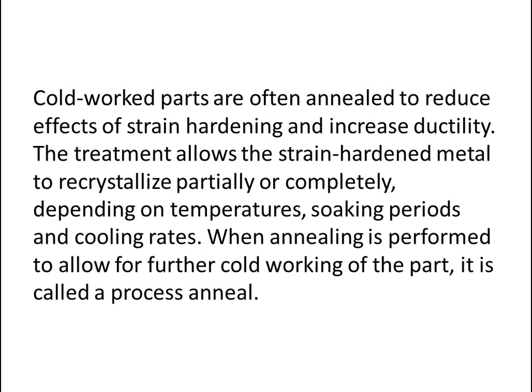Cold worked parts are often annealed to reduce the effects of strain hardening and increase ductility. The treatment allows the strain hardened metal to recrystallize partially or completely, depending on temperatures, soaking periods and cooling rates. When annealing is performed to allow for further cold working of the parts, it is called a process anneal.